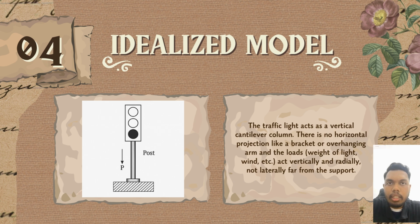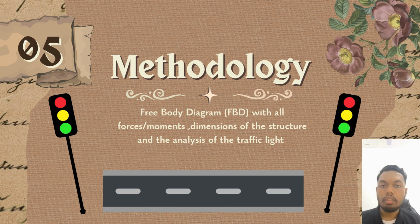And now I present the idealized model for the traffic light. In this model, we assume the post behaves as a vertical cantilever, meaning it's fixed firmly at the base and free at the top. This is commonly used to represent how poles behave in real-life structural analysis. There are no additional elements such as brackets or overhanging arms. All loads, including the weight of the traffic light and wind force, are considered to act directly along the pole, either vertically or radially.